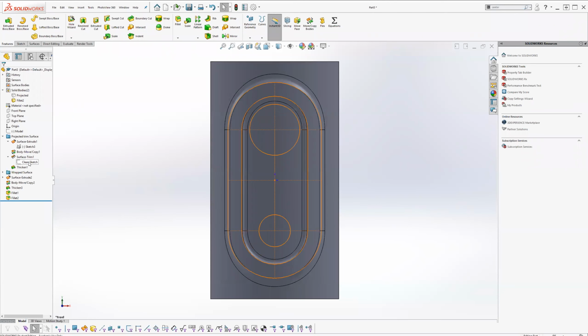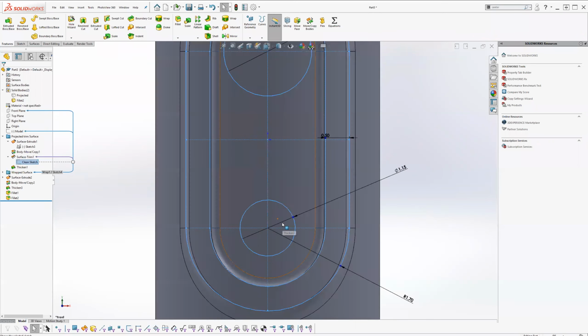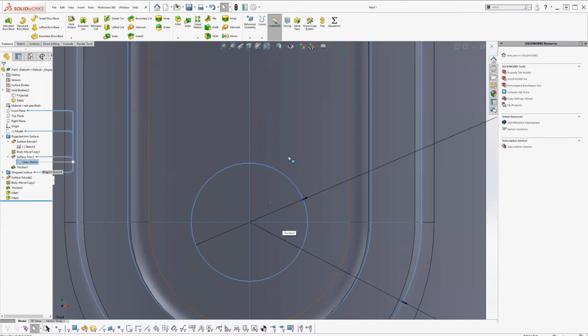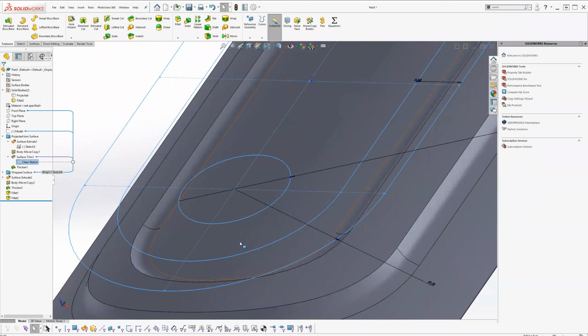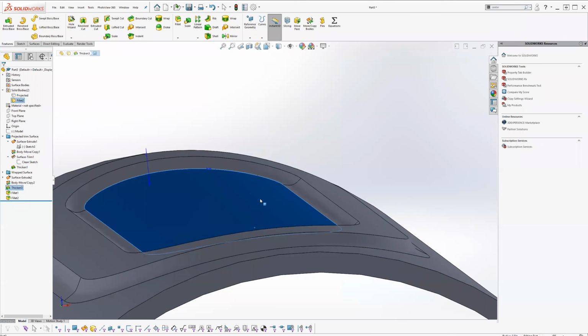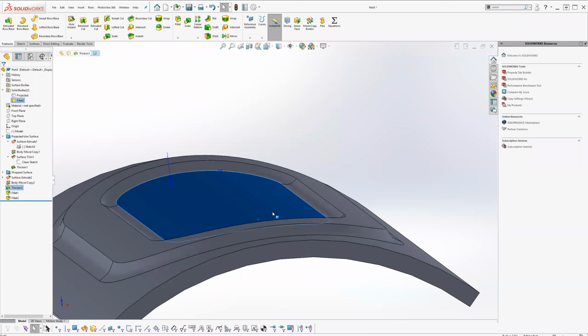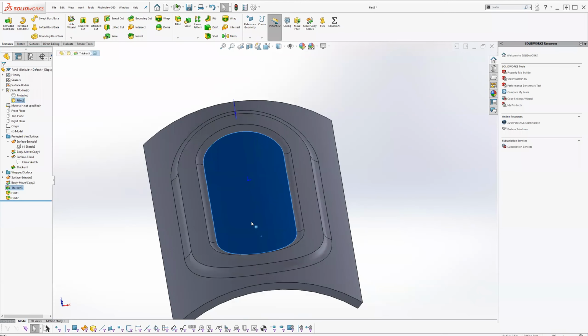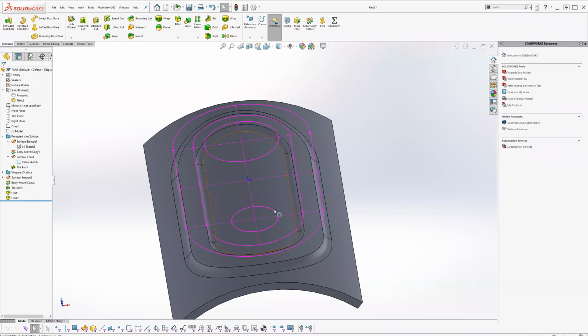Probably the easiest way to create this is to do a separation of this same surface. The surface is curved, and let's say I want this button to be the on button, and it's going to follow that same surface contour. It's going to follow the same contour, but there has to be a little bit of a tolerance to that. So I'm going to use that sketch. I'll show that sketch here. I'm going to use just that one element of it.